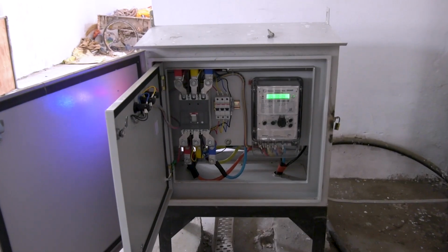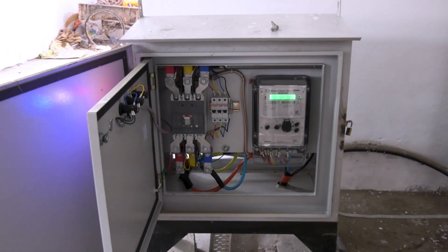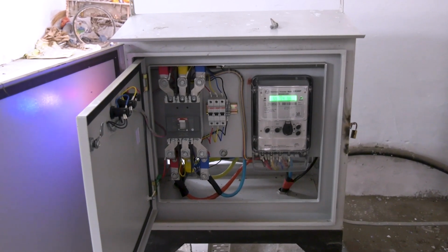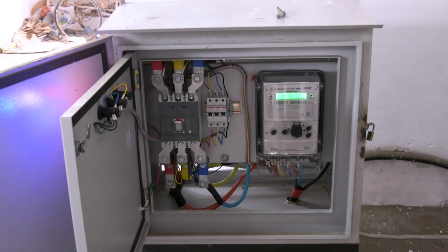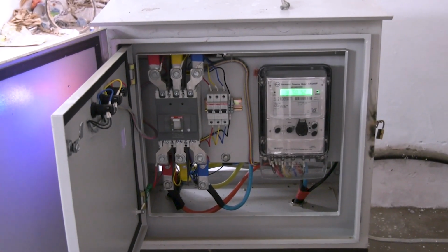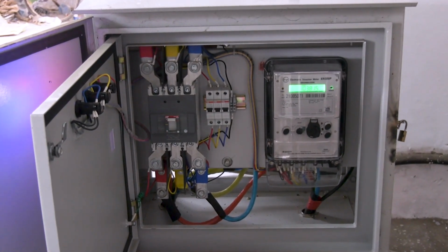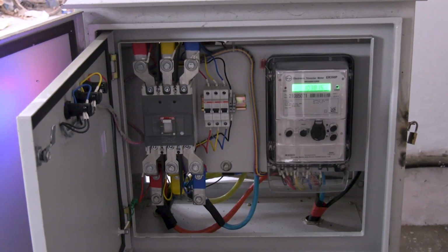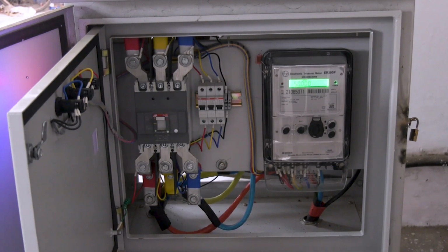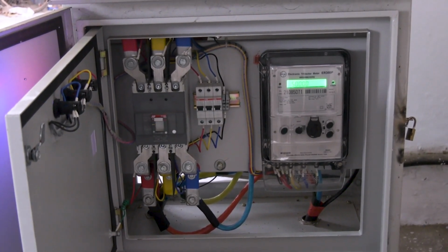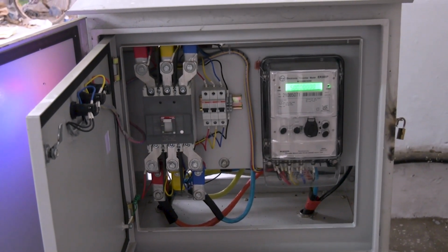This is an auxiliary AC distribution box, ACDB, installed by IIT Roorkee, designed to serve as a backup for the primary ACDB. It contains a similar setup with an L&T electronic trivector meter, that is ER300P, for measuring and recording electrical parameters. The meter along with the circuit breaker and terminal blocks ensure that measurements can still be taken if the primary ACDB encounters any issues. This redundancy is crucial for continuous monitoring and billing accuracy, providing a reliable secondary source for power consumption data.